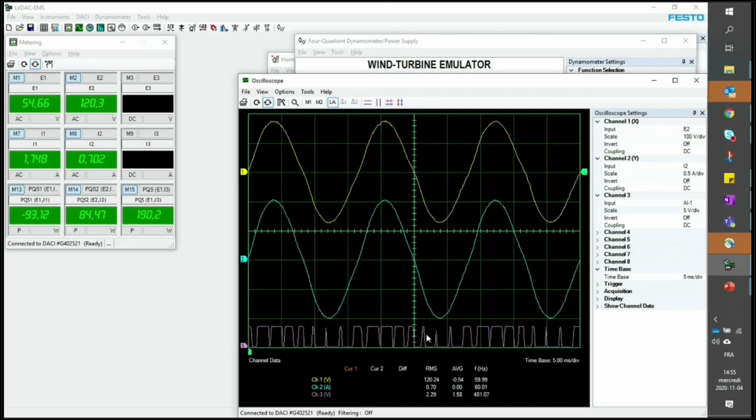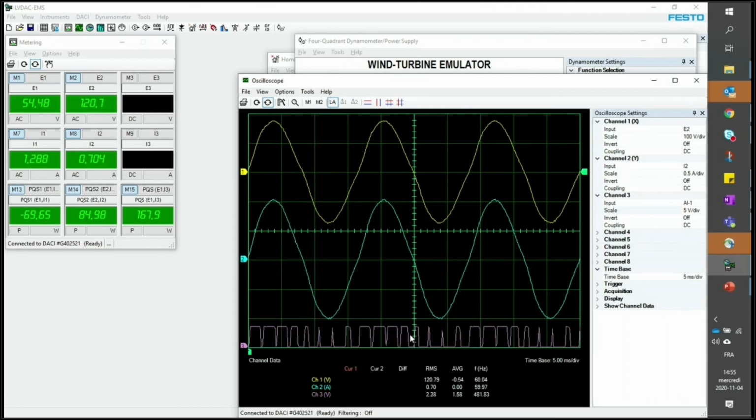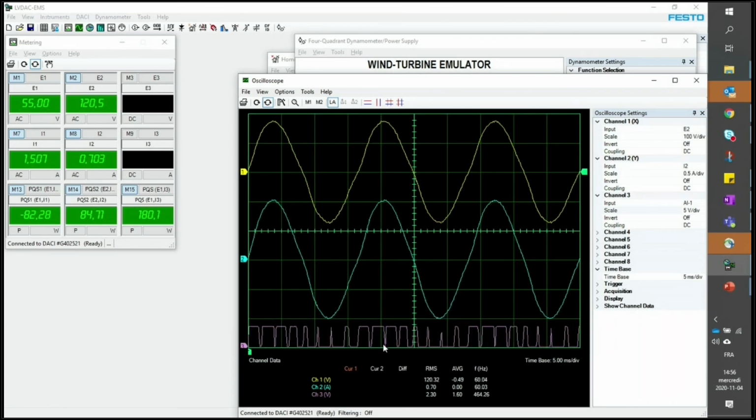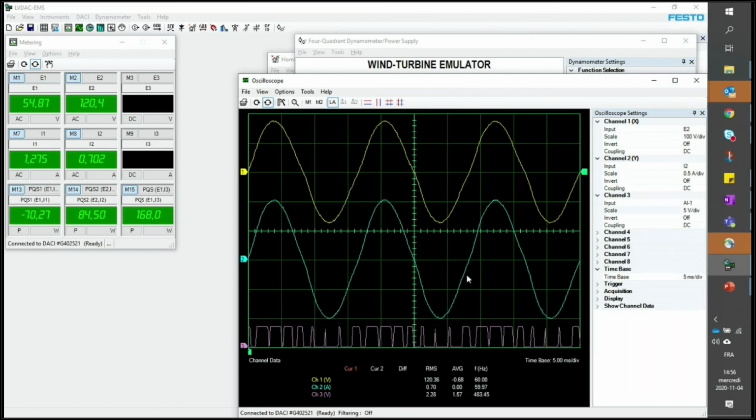And here are the triggering signals, the control signals sent to the chopper, sorry, to the inverter, one transistor of the inverter to produce these sine waves. So the students understand how the varying width of this pulse width modulation allows us to produce a sine wave like this. Of course, this is after going through the whole courses on power electronics. So normally they understand that clearly when they get to this point in their studies.